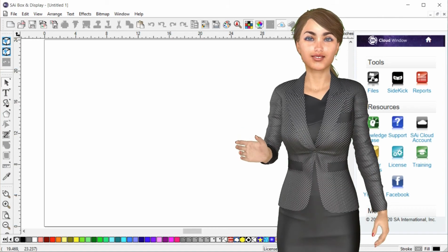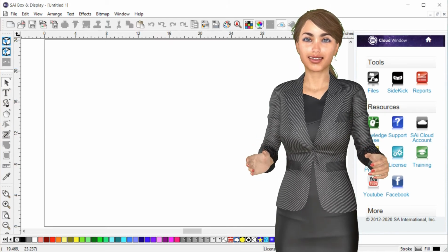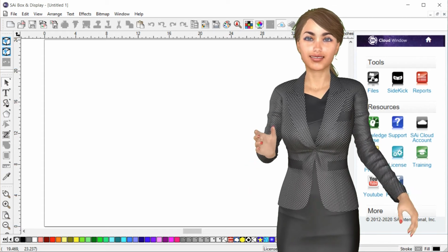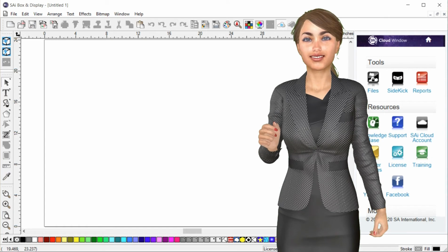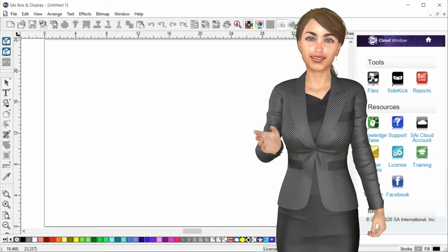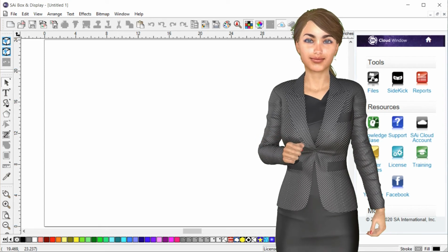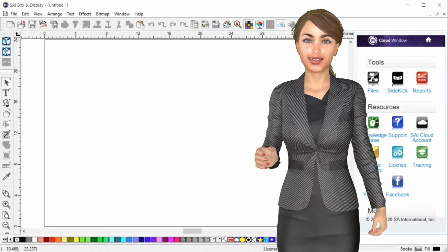This is the fourth and final video from our castle wall series. In this tutorial we'll learn how to use the perforation machine step to create the castle wall door. Next we'll use the add machine step, convert to flip up feature to create the drawbridge. Then we will learn how to set up the fold sequence order. And finally we'll position and fold our design in 3D. Let's get started.